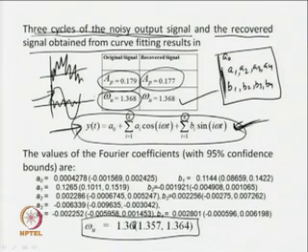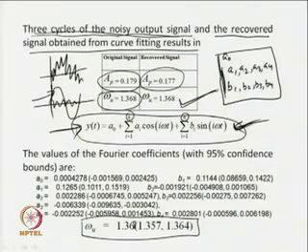That shows that using this Fourier series based curve fitting, it is possible to obtain correct information of the signal, correct limit cycle parameters from the corrupted signal, okay? Because the critical frequency or the ultimate frequency is obtained accurately and there is minor error in the peak amplitude, okay?